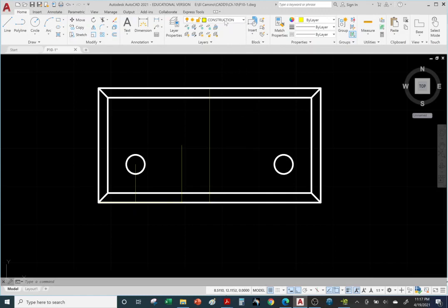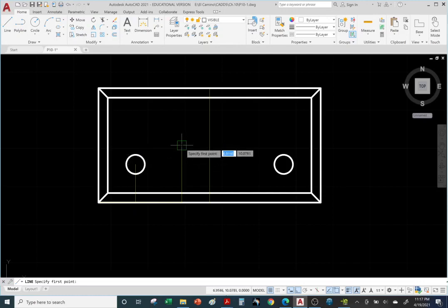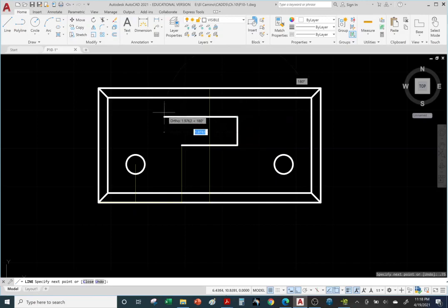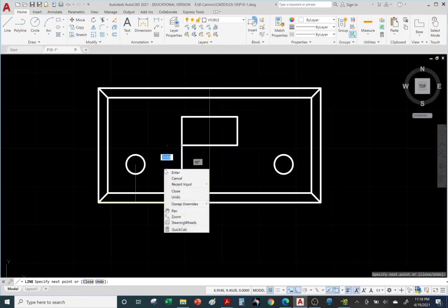So let's go to the visible object layer. Okay, and click. Okay, so using line command. Here's our starting point. Click. We're going to go 1.50 to the right, 1.50. Enter. Then go up 0.75. Enter. And back 1.50. Again, you don't put the minus because we're aiming left. Okay, so 1.50, going leftward. Enter. And then finally we close it. Click and right click enter.